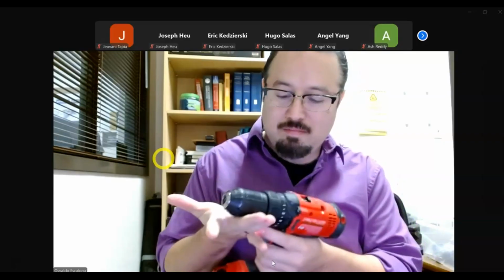Okay? So press the button, go forward. Press the other button, go backwards. Forward. Now, in order for us to open the chuck, you hold the spindle, put it on reverse, and hold the spindle with two fingers. Don't put a lot of pressure, just barely touch it. And I want you guys to notice what happens to the spindle. So I'm going to go. It opened up when I went reverse.